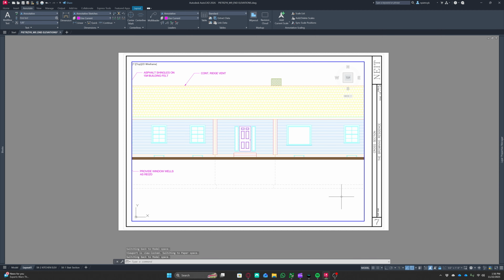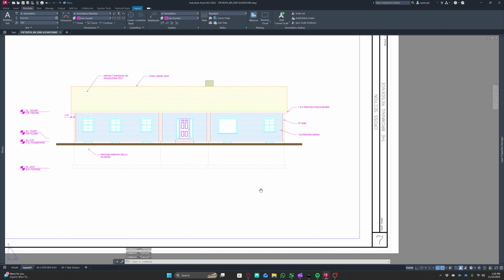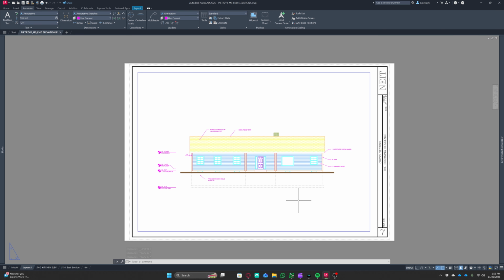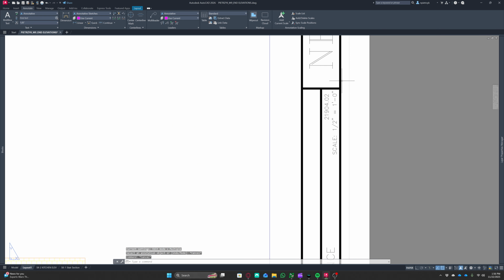But for example, like for milestone 7, I can go in here and just set this to be a quarter inch equals a foot. And this is what your submission for milestone 7 looked like. And milestone 8, technically. Milestone 9 is going to look a little different. So what we're going to do is, the first thing, I'm going to change this to milestone numero 9, I believe. My Spanish is terrible. My scale is a quarter inch equals a foot, so I'm going to change this to a 4.